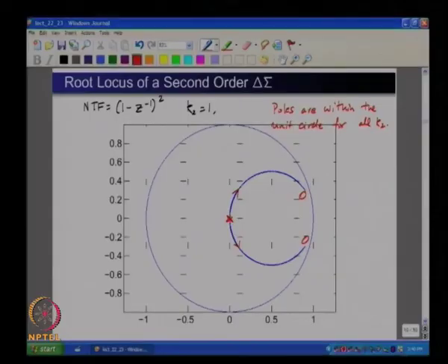We see that we are somewhere here, you can think of it as starting off here, and then these states will tend to decrease in magnitude because the poles are within the unit circle, correct, and as the states decrease, eventually you will come to a situation where you reduce the degree to which you saturate the quantizer, which means that the gain goes on increasing.